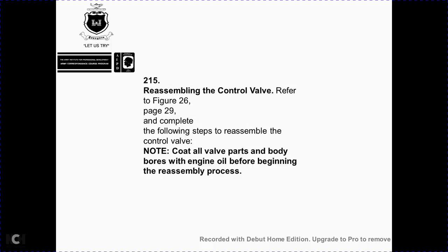215. Reassembling the control valve. Refer to figure 226 on page 29. Complete the following steps to reassemble the control valve. Note: coat all the valve parts and bores with engine oil before reassembling.